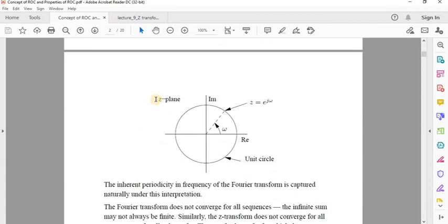This is called as Z plane. You have seen already. For example, in our control system practical, there is a practical to plot the zeros and poles of a transfer function. We were solving the characteristic polynomial in the denominator. We were finding out the roots. Roots are nothing but zeros and poles. Zeros are in the numerator and poles are in the denominator.